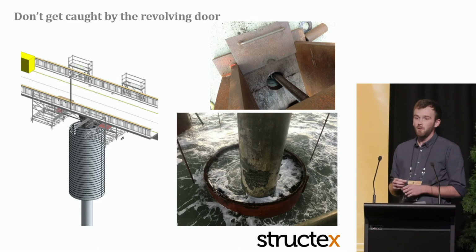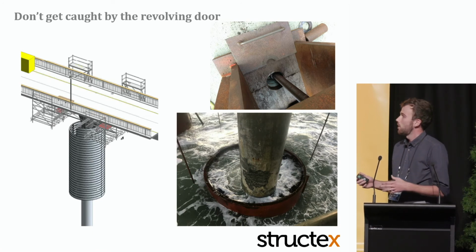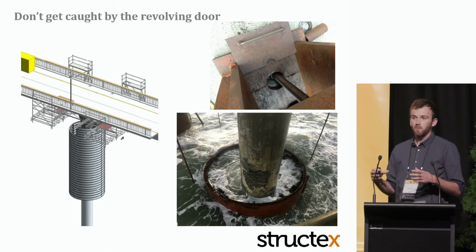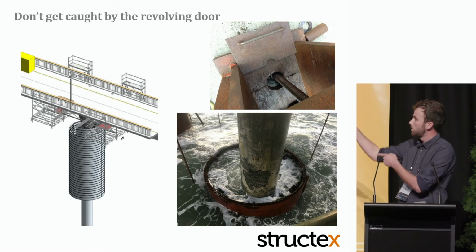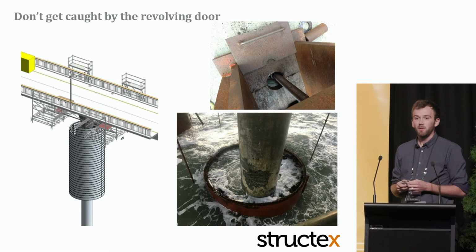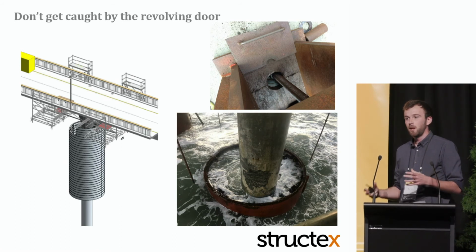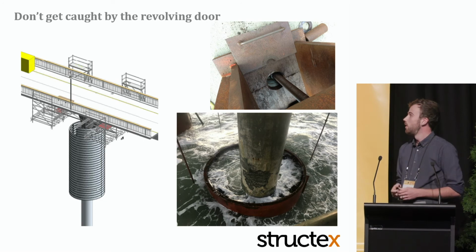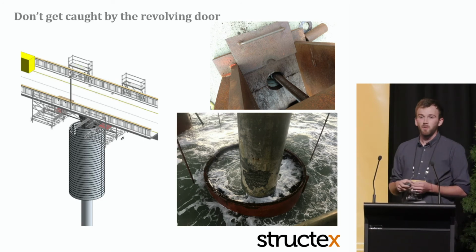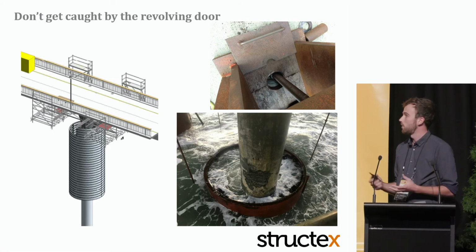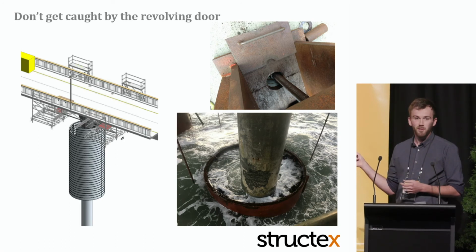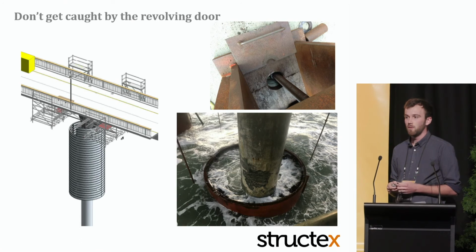And this is another one which was actually a failure due to those conversations not being passed on. So in this case, overnight, when we had no one working on it, we would basically let the bars go, you can see 2 bars coming down, and the caisson would be allowed to sit under its own self-weight. That was to stop the waves throughout the night eroding around the pile and causing them to become a big pendulum and basically batter into the pier. In this case, someone forgot to remove the plates and let it drop overnight, and so it became a pendulum and created quite a bit of secondary damage which had to be remediated. So it was another key reminder about having those core discussions and having them regularly.